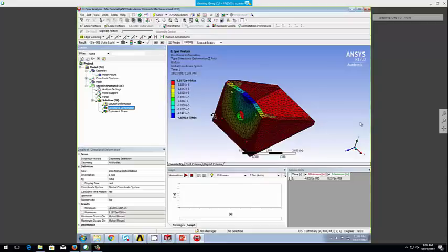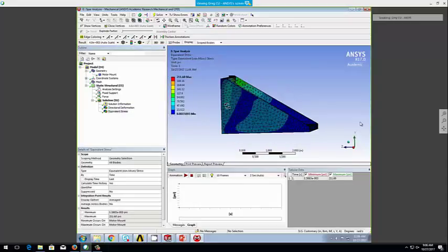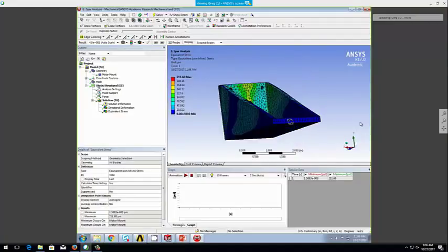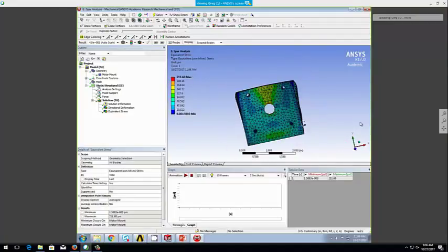The other thing you need to look at is going to be fits and finishes. So here's from another supplier, Rock West. There are some tolerances associated with here. Okay, so if I go to Rock West Composites and pull up their tolerance sheet, it begins to tell me what sorts of tolerances are held within their tubes. So if we look at a rolled tube, it can be plus or minus 0.006 inches between these diameter ranges.